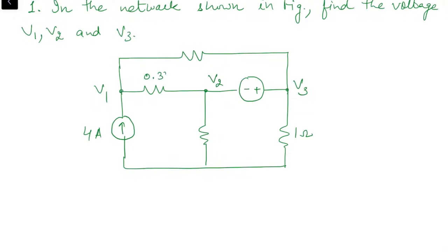So basically the nodes are already specified to us, node voltages are already marked. We don't need to identify how many nodes are there in the circuit, and we don't need to assign the voltage to them. It's already there in the problem. So we are already provided with the nodes and their respective voltages. We need to apply KCL to all nodes. So our first step is apply KCL to node 1.